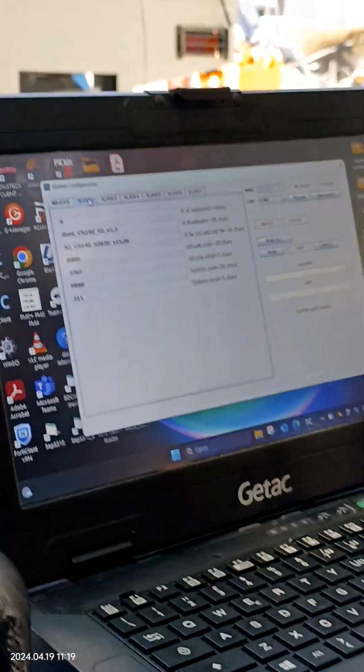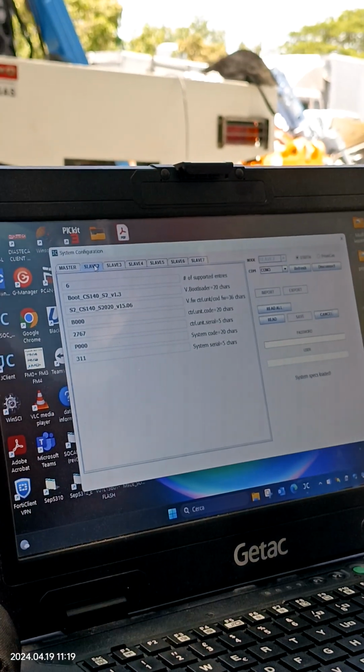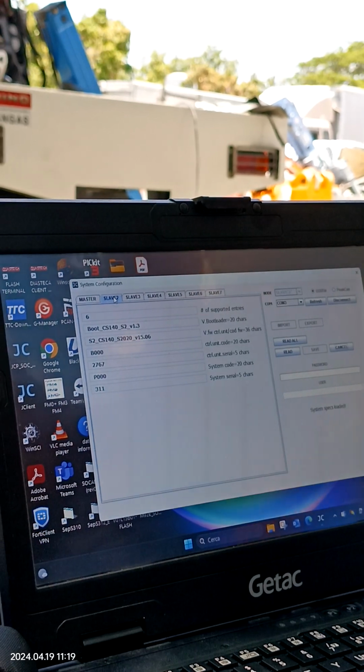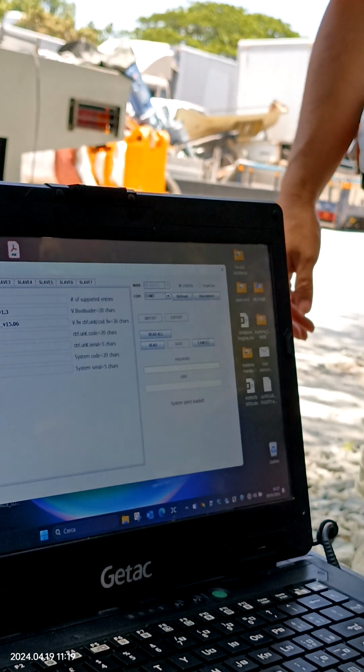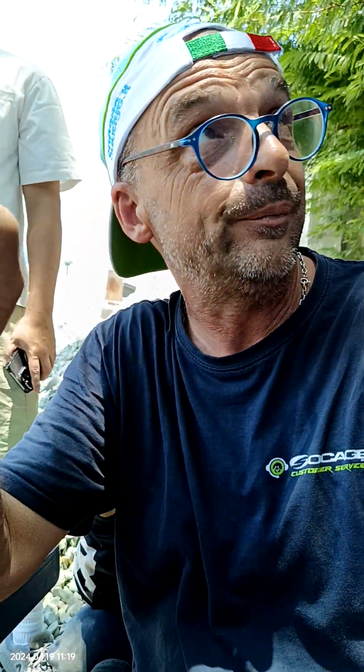Normally, if you order hybrid boards, it could be that you don't have the firmware, but you absolutely have the bootloader. For what? Because with the bootloader, you can install the board on the machine, switch on the machine, and load the firmware directly.